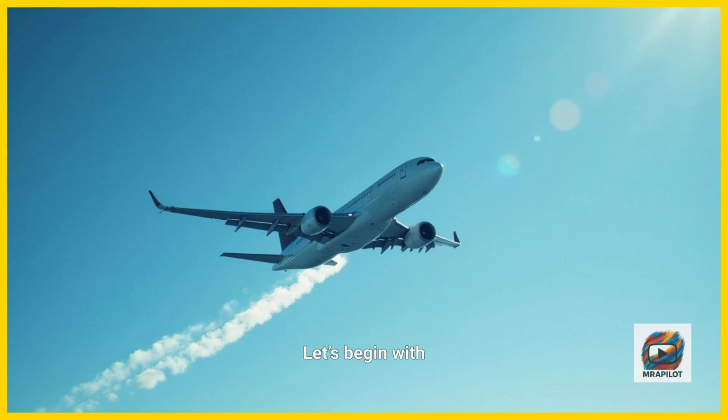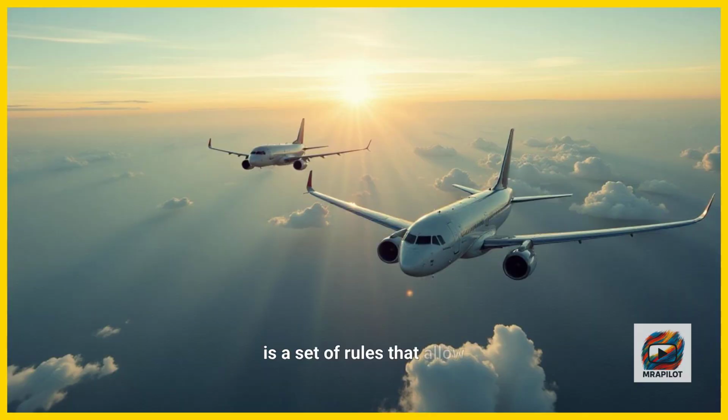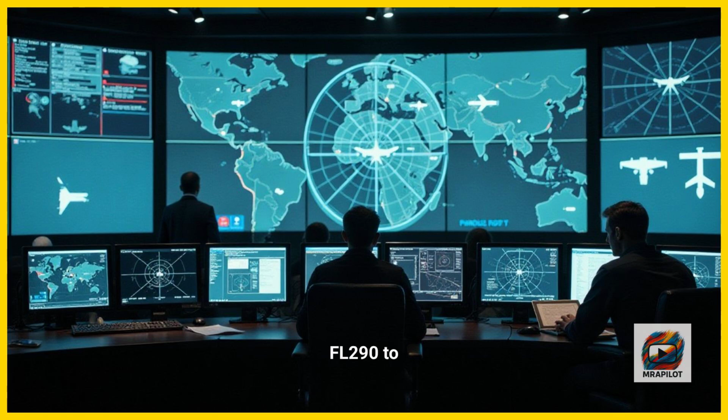Let's begin with RVSM, reduced vertical separation minima. This is a set of rules that allow aircraft to fly with only 1,000 feet of vertical separation between flight levels from FL 290 to FL 410. It increases airspace capacity and efficiency.